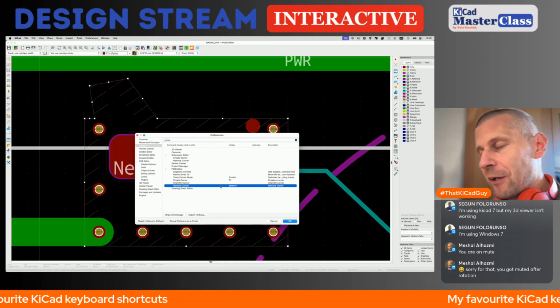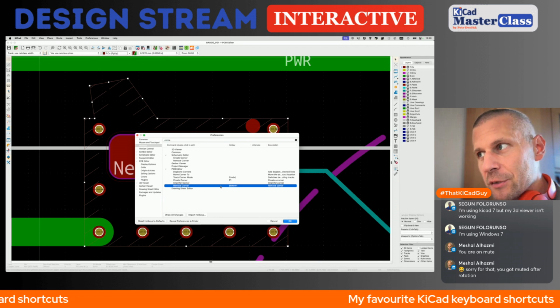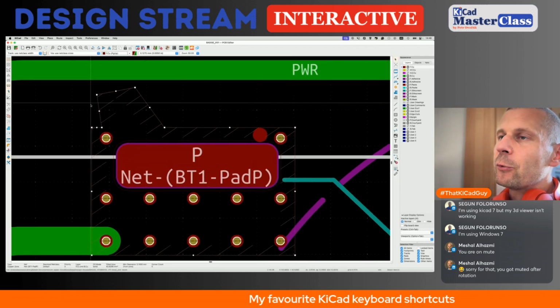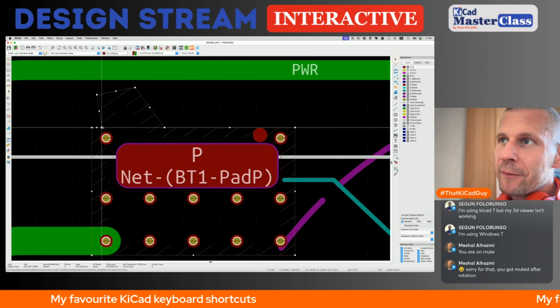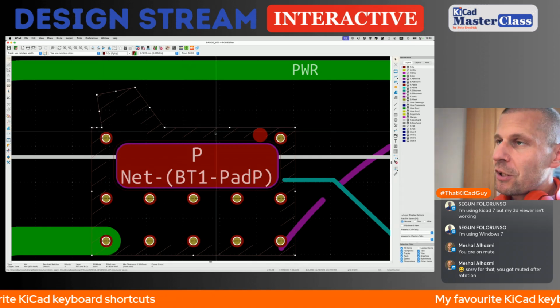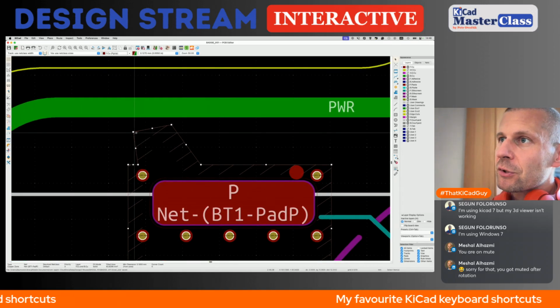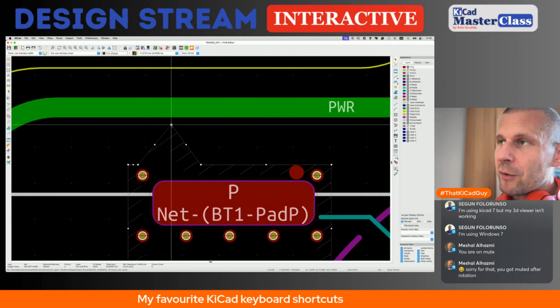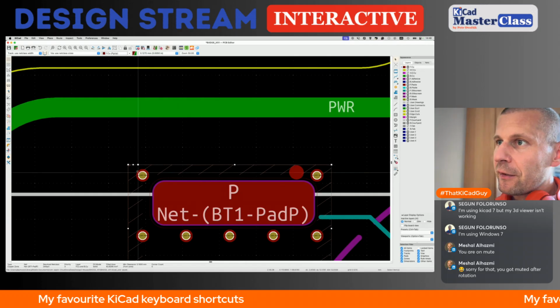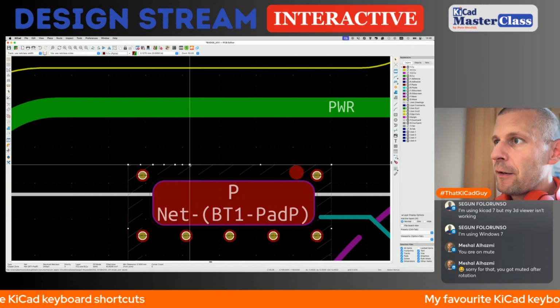So F1 is adding corner, and shift F1 is removing. It's very useful when I edit my polygons, and for instance, I want to change the shape. By holding shift and pressing F1, I easily remove all the extra corners.